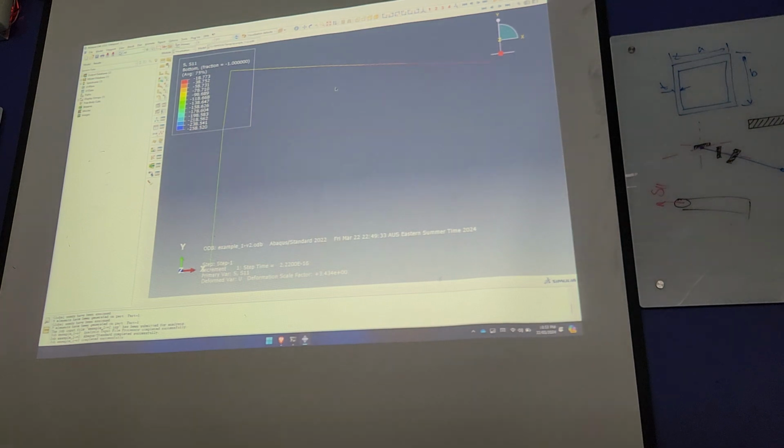You need to first, in the material, right, you need to assign two sections. One is beam and one is truss. Okay, so here, right, you need to go to property, this one, the manager. So you need to create this. If you don't have this, you cannot run at all.